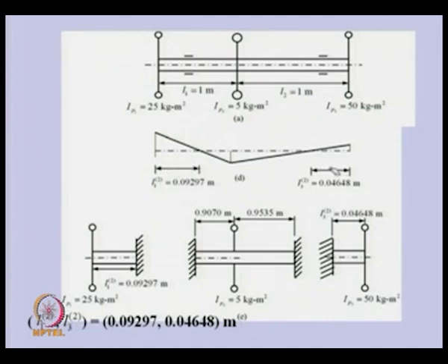You can see that if a node is here and a node is here, this system can be broken into 3 single rotor systems. Because we know the length of this, the natural frequency of this can be obtained, or of this, or even of this, and they should be the same as the natural frequency of this system.